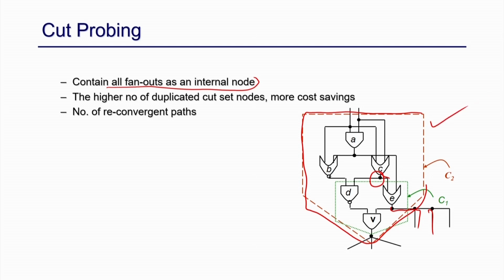So that makes it a better cut. Also, the other example that I just gave here: for this cut, if I find multiple inputs coming from a single source, which is also good, right. That means I am not going to select all of them coming here. The chance is high that the number of inputs of this cut is less, because now I can consider both of them as a single input and I can select something else as well, right. So, this is also cost saving, and it has a positive impact on the cut.